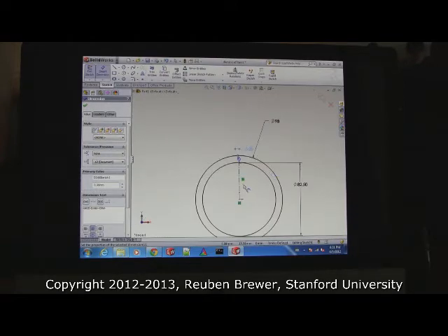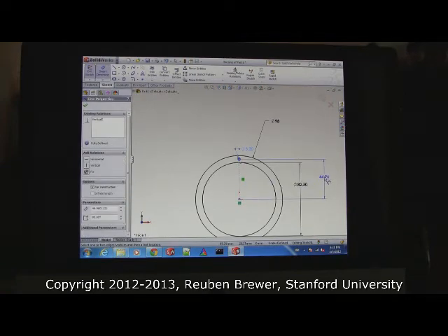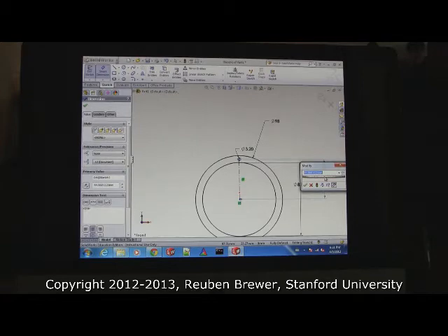Now I want you to take the Smart Dimension tool and click on that line. And I want you to set that distance to 45. And you'll see when you do that, it turns black. Is everybody there? Okay, so vertical lines and horizontal lines are the easiest lines. They're easy because SolidWorks helps constrain them. Now say you want to go to 22.943 degrees. It does not, thank God, have an automatic suggestion for that.